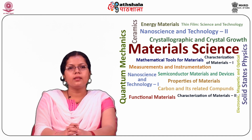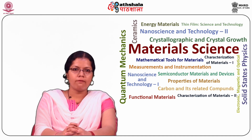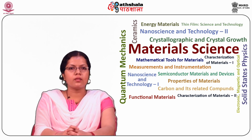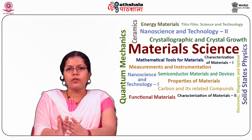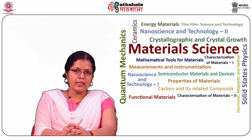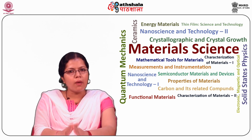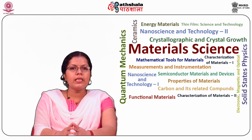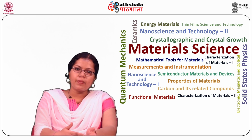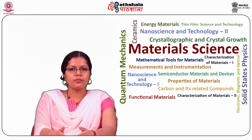Now, let us see the construction of the electrodynamometer wattmeters. First, the fixed coils. The fixed coils carry the current of the circuit. They are divided into two halves. The reason for using fixed coils as current coils is that they can be made more massive and can be easily constructed to carry considerable current, since they present no problem of getting the current in or out.